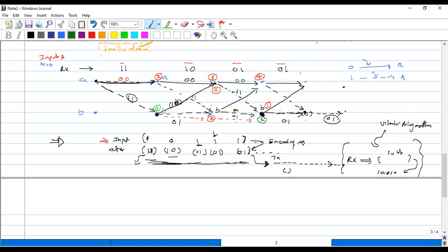I will stop this calculation because this is 4 and 5, because we need to get the minimum Hamming distance weight. So calculating the Hamming distance through this branch we can stop. Now I stop here. But here I have 3. If I go through this, I have 1. Yes, this should be 1.